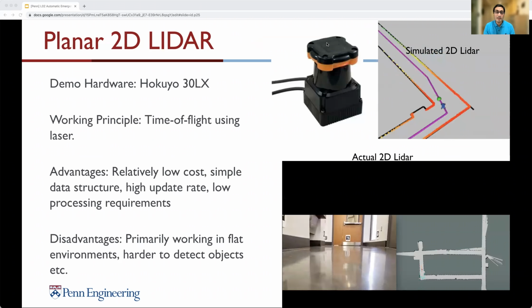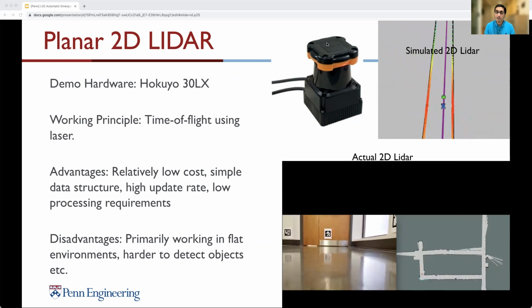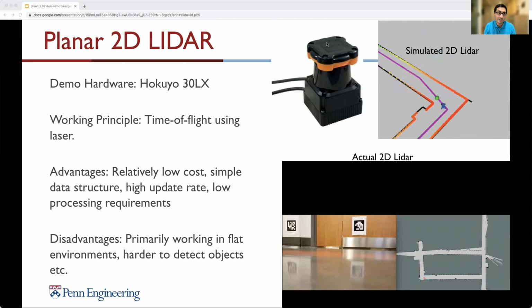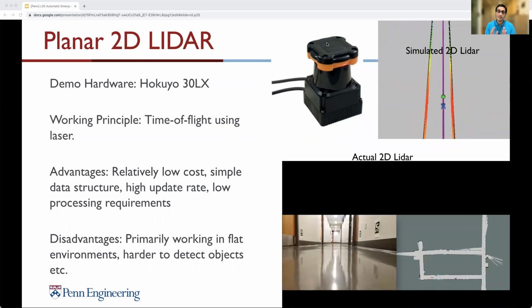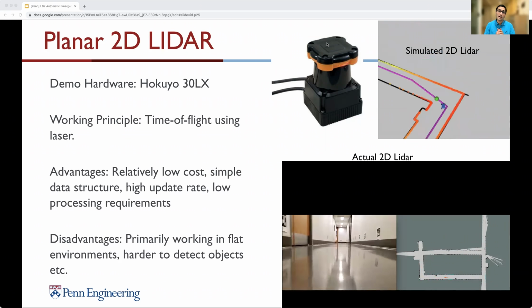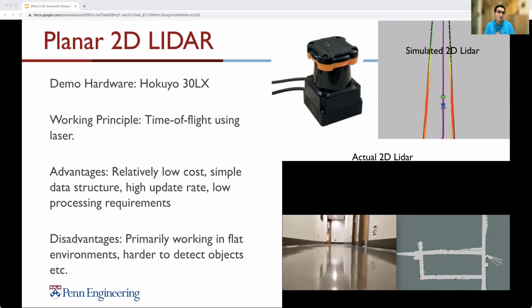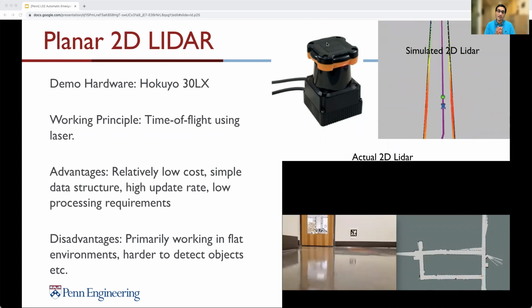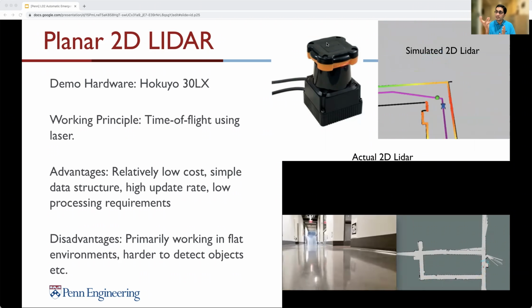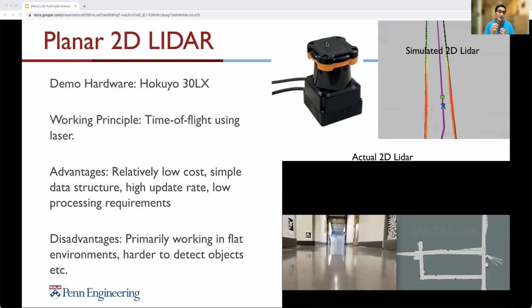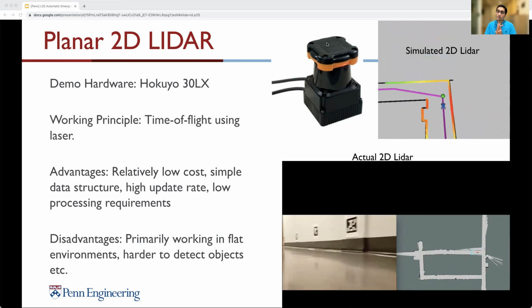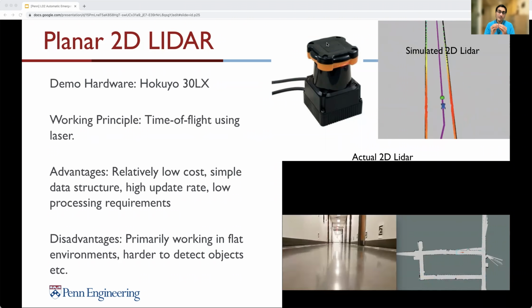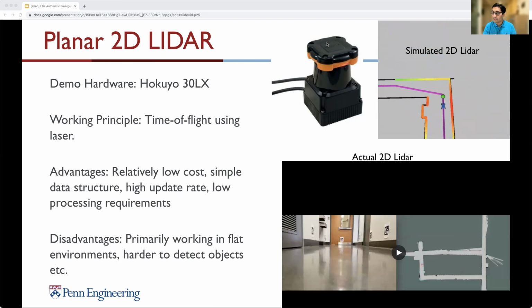The LIDAR, depending on whom you ask, stands for light radar or light detection and ranging. A LIDAR provides depth or distance information: how far from the car are the objects in the scene. This is one of the most important sensors in the field of autonomous driving. Traditional LIDAR systems are electromechanical systems, which basically are a spinning laser system. They emit photons which reflect off objects, and the time when they reach the collector is used to provide a very accurate distance estimate. The moving parts restrict the size and also make it a pretty expensive sensor.